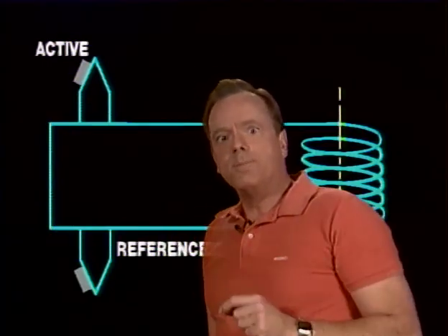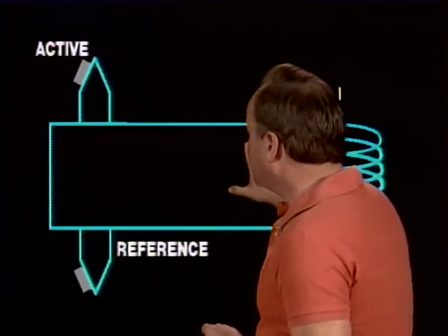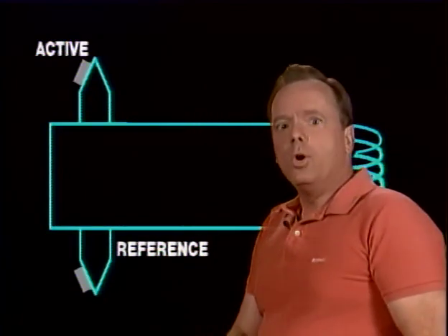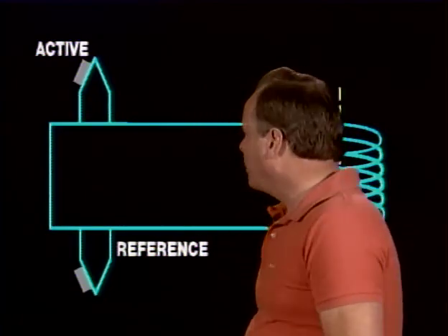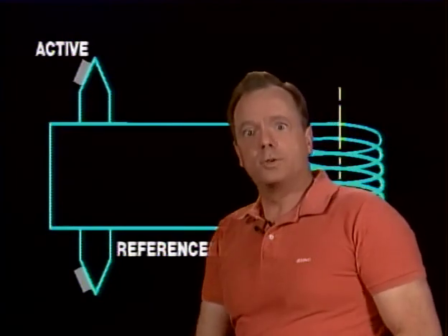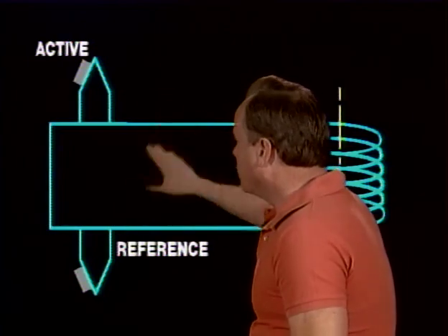All right, now let's talk about temperature indicating systems again. We mentioned earlier a thermocouple type system, and the advantage of a thermocouple type system is that it requires no power source. Thermocouples, by the way, are used for no electrical power source. So if the electrical system fails in this airplane, you still have this gauge working properly.